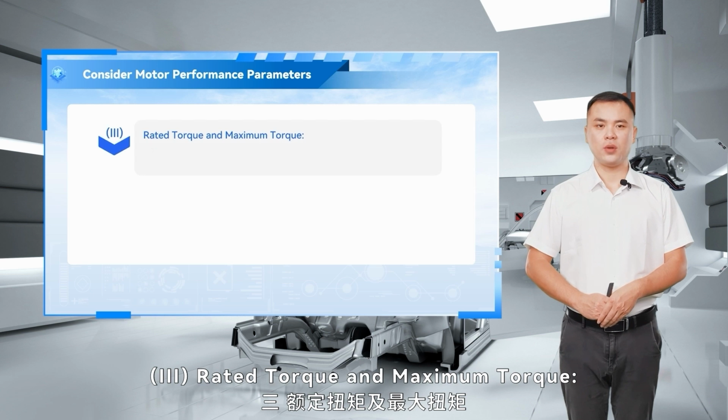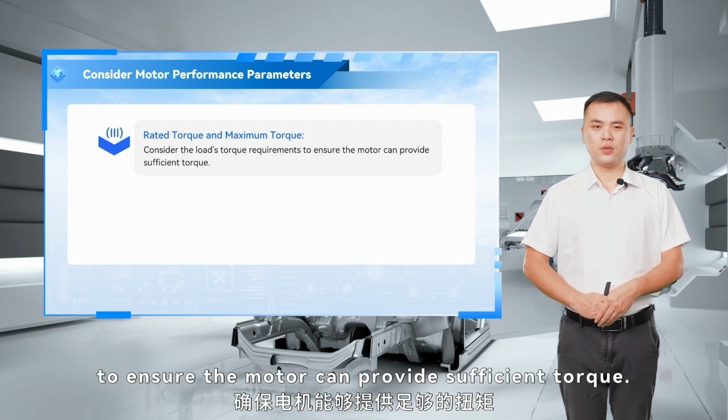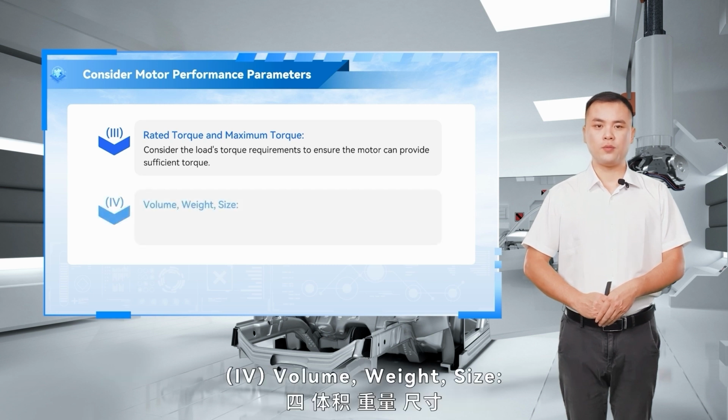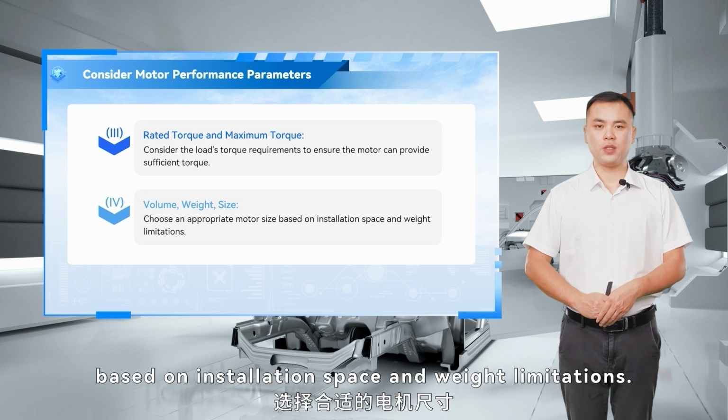3. Rated torque and maximum torque. Consider the load's torque requirements to ensure the motor can provide sufficient torque. 4. Volume, weight, size. Choose an appropriate motor size based on installation space and weight limitations.